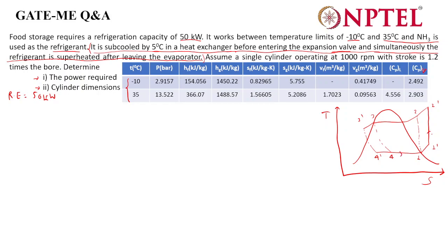The flow goes this way. So first let me know what would be the refrigeration effect in terms of enthalpy here. Can anyone tell? H1 minus H4 dash, right? Yes, sir. So what would be the power input? Energy input, I can say. H2 dash minus H1 dash.